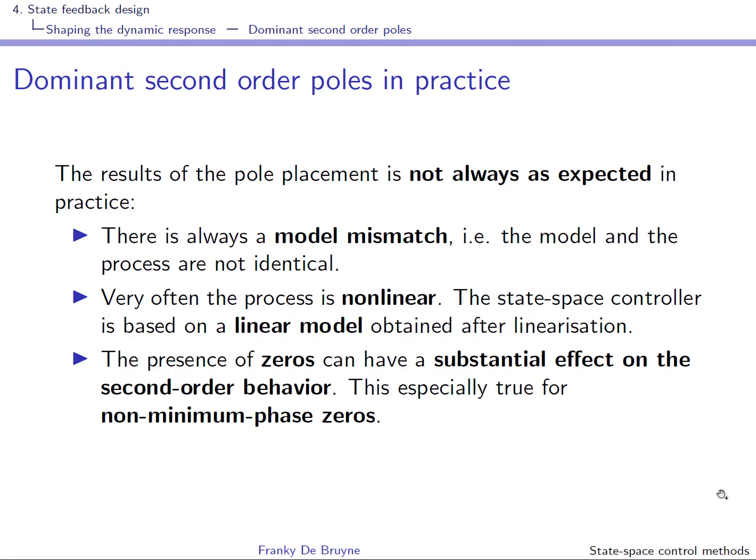A very important comment is related to this second item over here. When you're going to test a design in simulation, please always test it on the non-linear model. I very often see students test the design on the linear model, but you know that the non-linear model will be closest to the actual system.